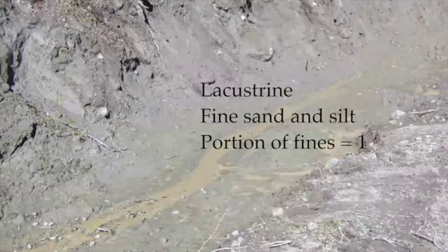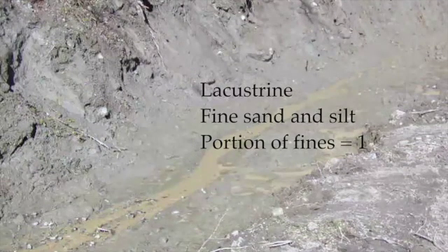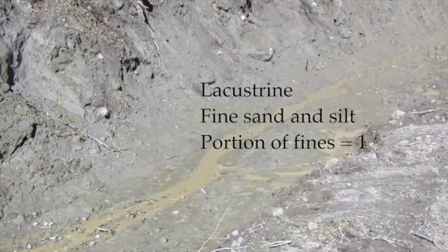The ocean level was at about 140 to about 250 meters above its present level at the peak of the last glacial epoch. Around the whole of the Georgia Strait, there are old deltas, lacustrines, and marine materials everywhere at higher elevations than you might otherwise expect. You can get some pretty unpleasant surprises where you run into marine blue clay because these materials behave badly when they get wet.